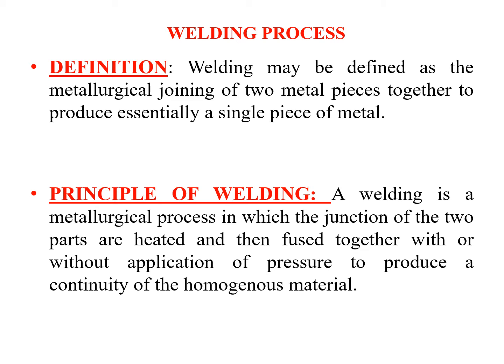So welding is a process of joining similar metals by application of heat, with or without application of pressure, and addition of filler materials. So the result is a continuity of homogeneous material of the composition and characteristics of the two parts which are being joined together.